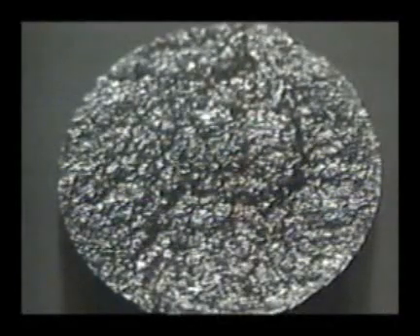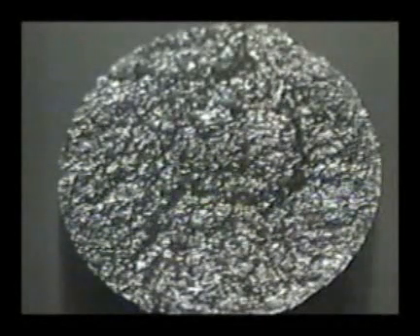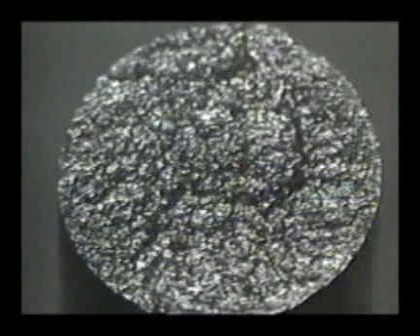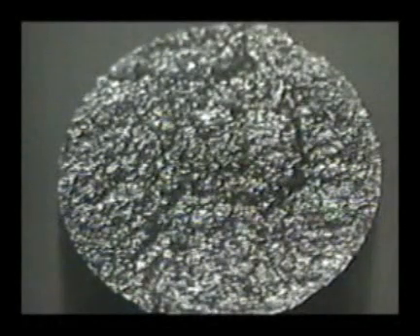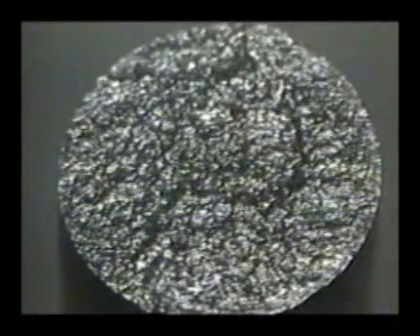Sometimes there are no chevrons or impact damage to guide us to the initiation site, and we have to examine other parts for clues or road signs to help us understand what happened. We should also remember that most cleavage fractures are a result of another problem and are not the root cause of failure. Finding the initiation site of an intergranular brittle fracture is often very difficult.